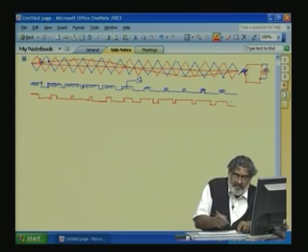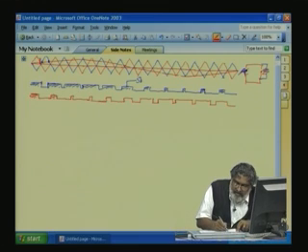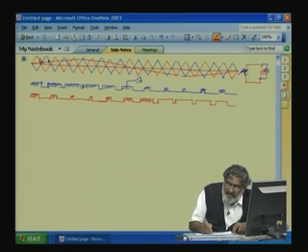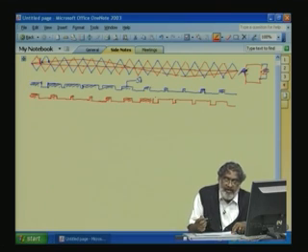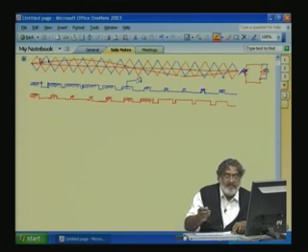So, this way. Whenever the sine is greater than the triangle, sorry, the bottom switch is on, but it is the reverse of the other phase.